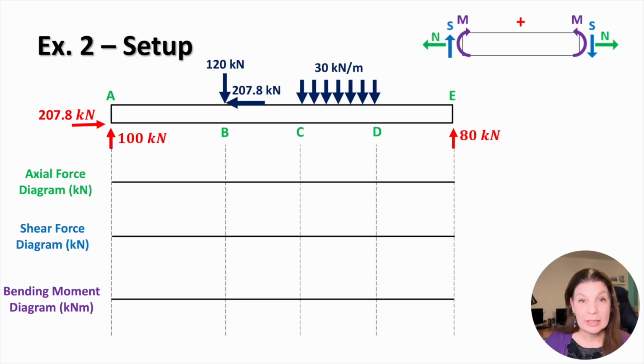Once again, before writing the equations, we'll set up the structure of our solution. We'll draw the free body diagram and leave space below for the axial force, shear force, and bending moment diagrams. We'll once again mark the boundaries between regions using dashed lines, which correspond to the boundaries of the section cuts. As we analyse each section, we will progressively build the internal force diagrams.